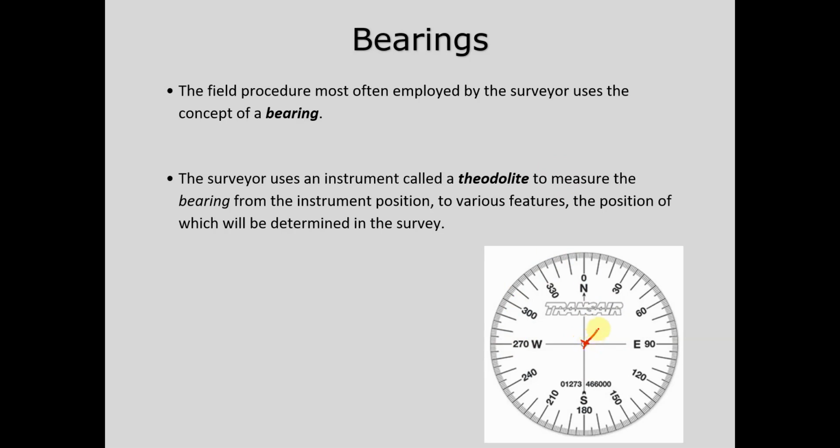So from this starting point, if I draw a line that way, by specifying this particular angle, what we call our bearing angle, let's call it theta for now, that will say this is the center line of the road. And now by knowing the length of that road, for example from here to there, say it's 100 kilometers or whatever, that will specify exactly the starting point and the end point of that road. Because by specifying the length only, this road could start from this point here, but could end at any of these points with the same length. So this is a quick overall view.